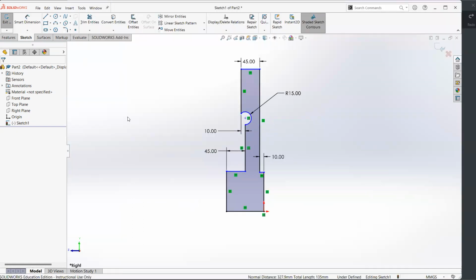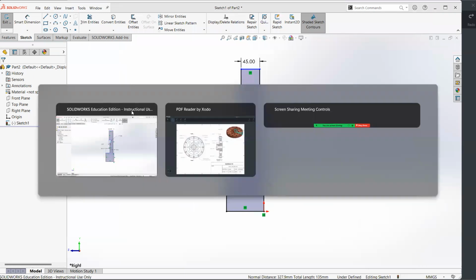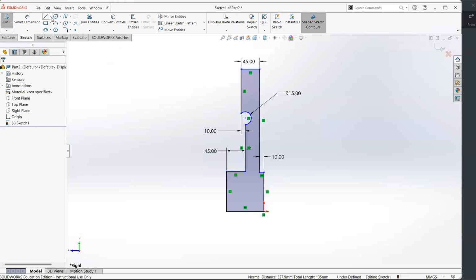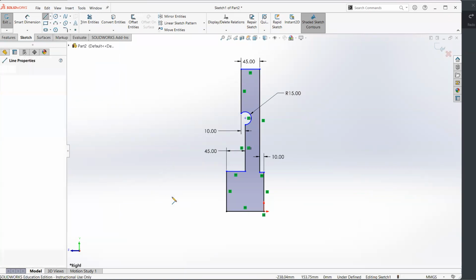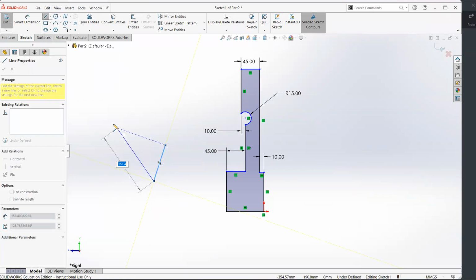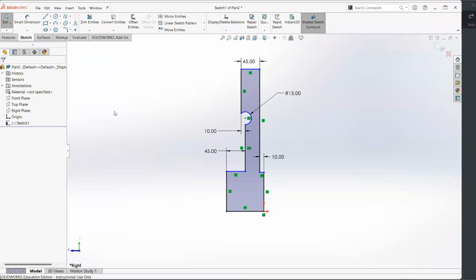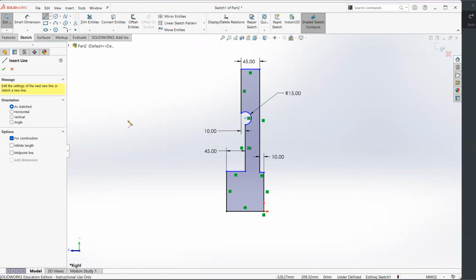However, instead of calculating this for every part, you could simplify it by using a center line. So we have this normal line that we are using, but there's also what we call construction geometry, which helps us to create our part, but is not part of the part that we are modeling.